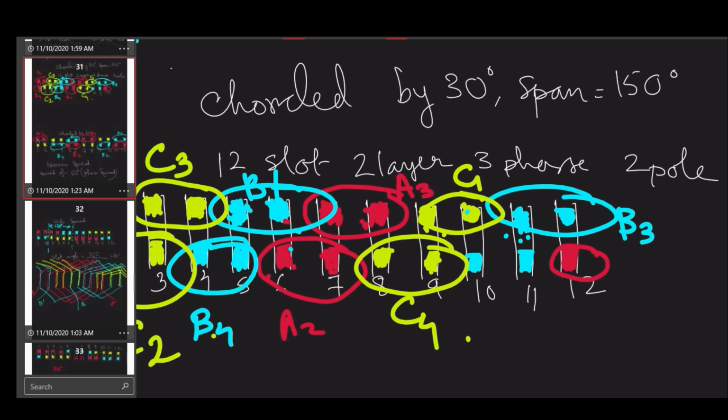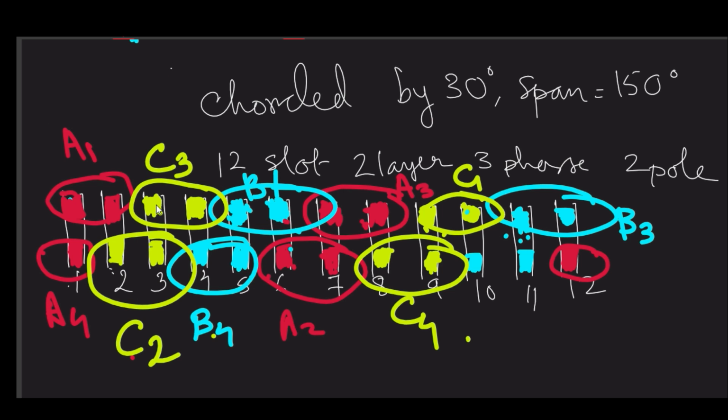So what I'm trying to say, it's a very simple thing: once you cover two poles, each of these slots consumes a 60-degree angle spread. So once you reach the end, you have a total of 360 degrees. Now it is easy to understand that